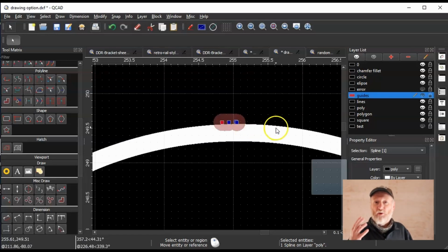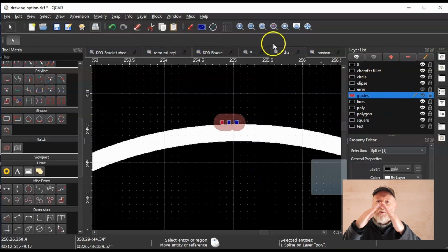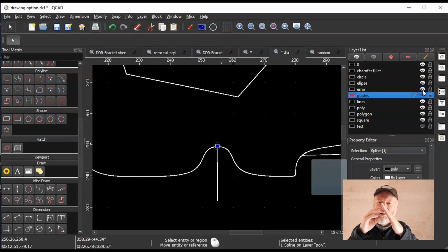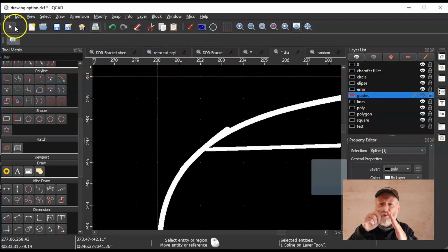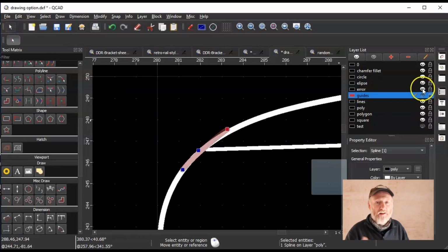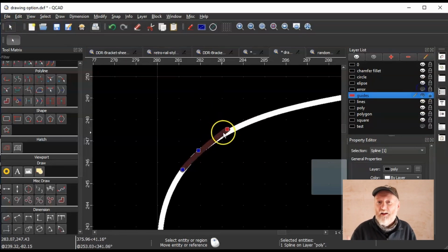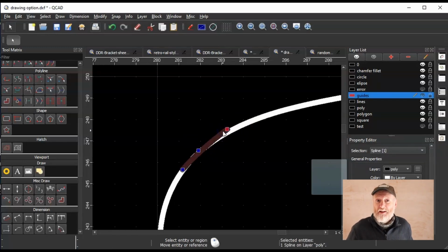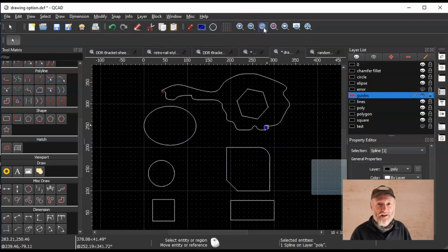Now the other type is something we call a dangly end. Dangly ends usually mean it's where you've had an intersection, the lines that meet, and you've shortened one or changed one, and there's a little bit, just a tiny amount, that sticks out. It could be micromillimeters long, literally one dot away from the end of a line, but that dangly end can be a real pain. Now in this example, the second one here, I've drawn it as a line over the top of the original line with a little bit sticking out, but it gives you a similar sort of idea. And believe me, these are extremes that I've drawn here to show you. In reality, these things could be microscopic to find and fix. Trust me, I've been there.